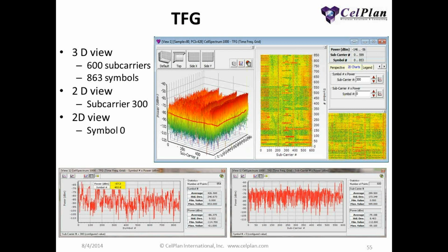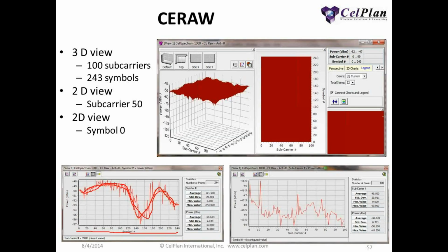Although there are some fast fadings, there is a slow fading that takes several frames, because remember we are only representing the reference signal, so this is a distance of 6.1 frames. So it takes several frames to fade in time, but in frequency it really fades every, I would say, 3, 4, 5 subcarriers. You have large fadings and so on. This is very important information for us to design our system.